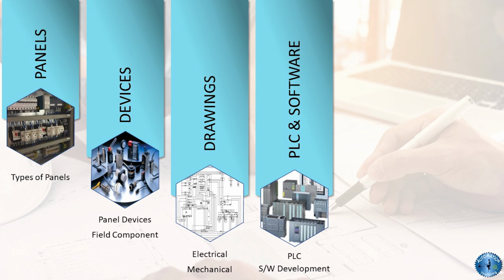Initially, the PLC was used to replace relay logic, but it has an ever-increasing range of functions in many more complex applications. The structure of a PLC is based on the same principles as those employed in computer architecture. It is capable not only of performing relay switching tasks but also of performing other applications such as counting, calculating, comparing, and the processing of analog signals. Programmable logic controllers offer several advantages over a conventional relay type of control.